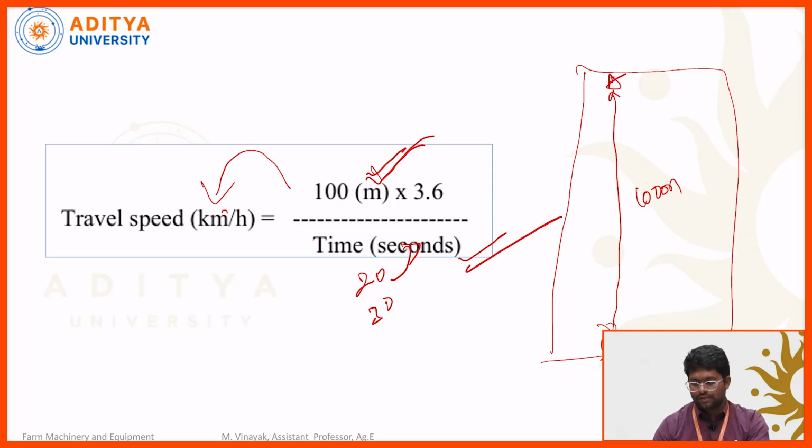During the process of covering the A to B point, whatever fluid was delivered from the spraying machine will be collected through the jug. Based on that particular area, we need to calculate in hectares. Initially, in the 100 meters area, we need to cover the liters per 100 meters.